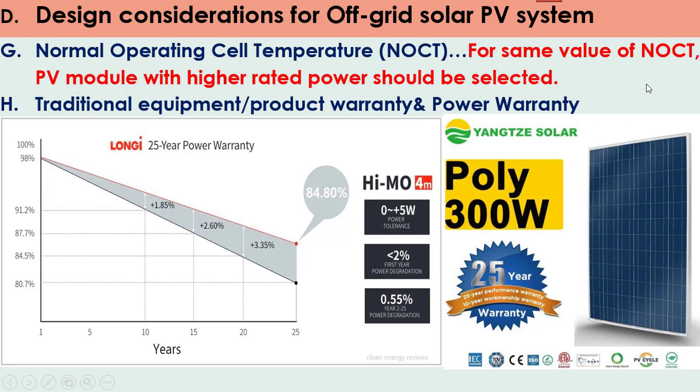For the same power of more than one module, we must select the module with higher normal operating cell temperature, in order to make our assurance that this module will be able to work at base condition and hotter climate condition.